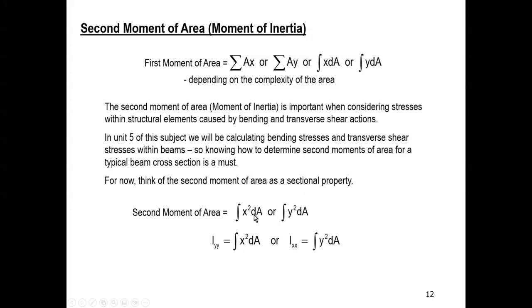It's very uncommon that you have to do this from the mathematical relationship. In real case problems, you calculate that using the tables, or using the primitive shapes. So we start the definition of the second moment of area by introducing some primitive shapes like rectangle, circle, triangle, and then we go through the compound shapes.